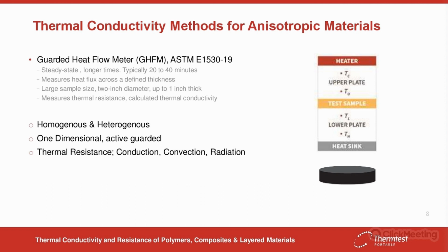Through the measurement of resistance, you can see effects of conduction, convection, and radiation. Are those phenomena desirable? No, but at least in the description of resistance, it's more appropriately measured. One of the comments not to miss out on is that there is a paste applied to this method. Through the procedure of calibration, the effects of that contact paste are removed against known materials.